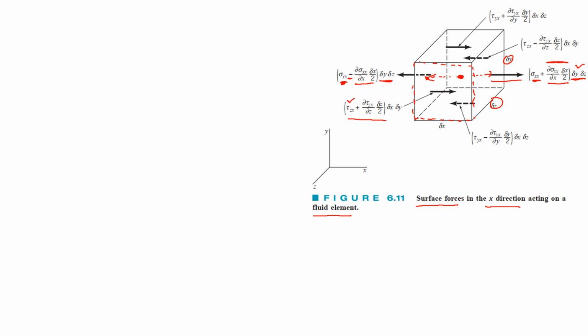This is the shear stress at the center, and these two subscripts, the z shows the direction normal to this plane, that is along the z axis, and the x is the direction of this stress, along the x axis, and this is the gradient of this shear stress as it moves in the x direction, and the area A. Similarly, this stress right here represents the gradient of the shear stress along that back plane.